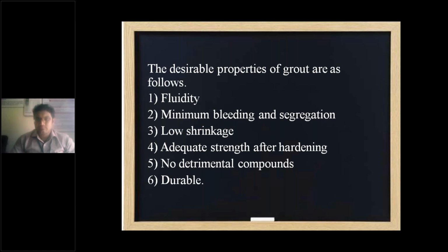And next one, minimum bleeding and segregation. Third one, low shrinkage. Fourth one, adequate strength after hardening, no detrimental compounds, and durable. The grout material should be durable. So these are the properties that the grouting material should have, right?